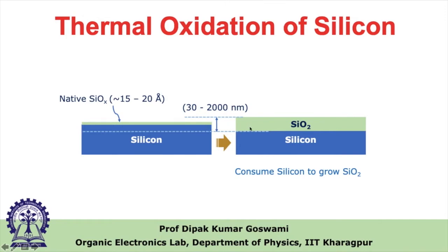That's very important. When you convert silicon into silicon dioxide, the thickness actually increases for an obvious reason: silicon gets oxidized, and you have silicon dioxide, two oxygen connected with silicon, and therefore the volume increases, right?